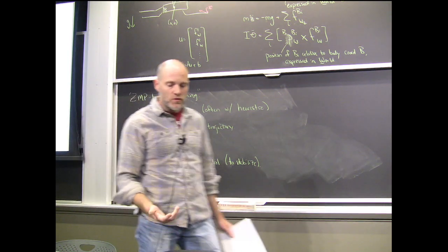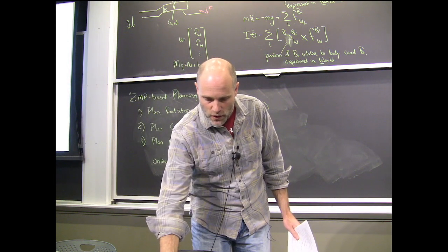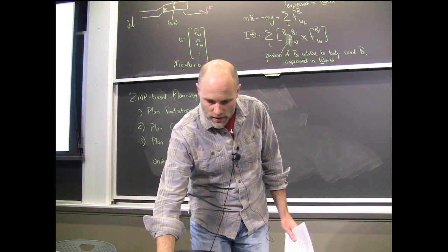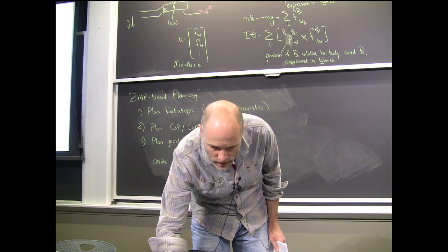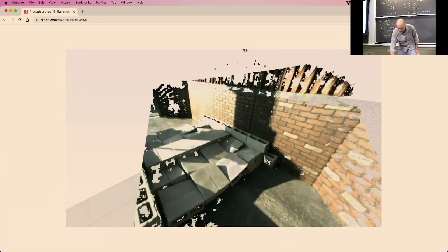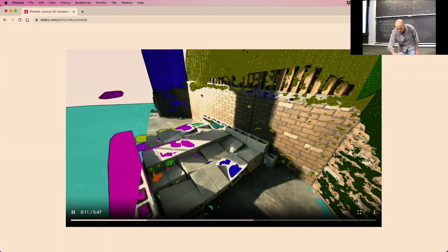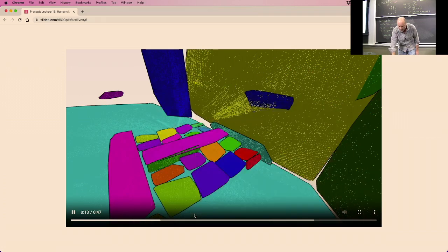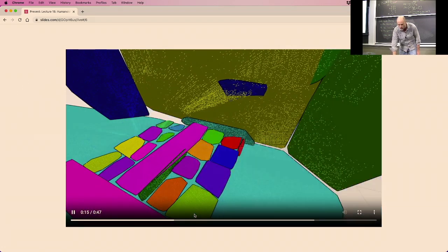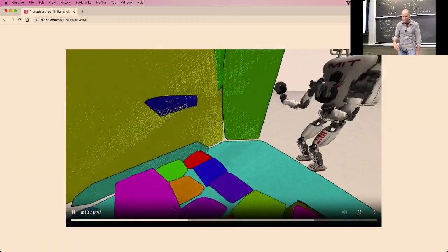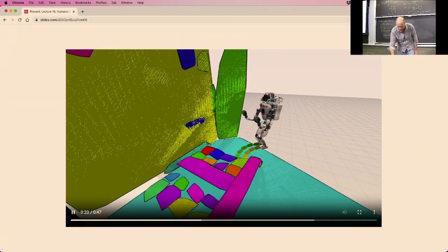So there's lots of interesting ways that people have done footstep planning over the years. Let me just show you that pipeline in action on our Atlas robot. You'll see as it walks up to some terrain, it first looks at the terrain. There's a perception step I'm ignoring today. Okay, it looks at the terrain. It tries to perceive roughly where the steppable regions are. Okay, and then it does a footstep plan first. Whoop, it puts down some footsteps.